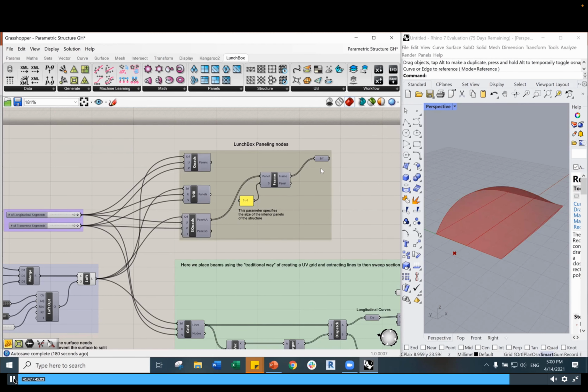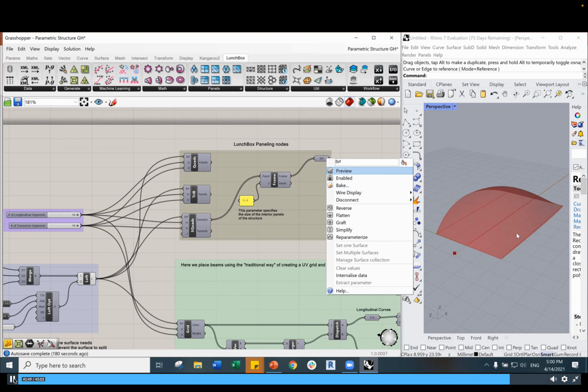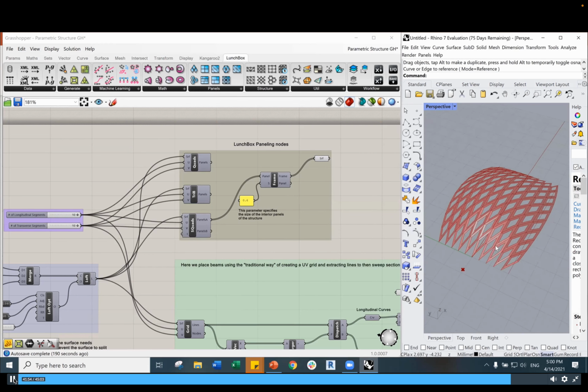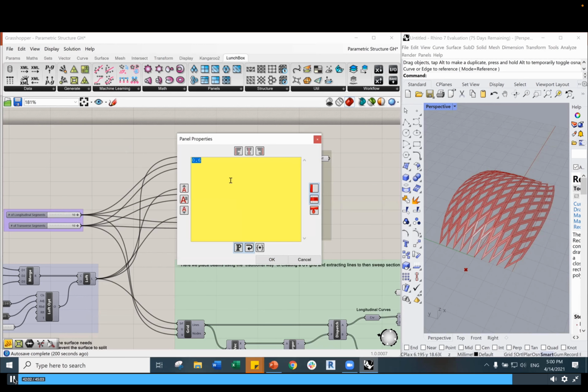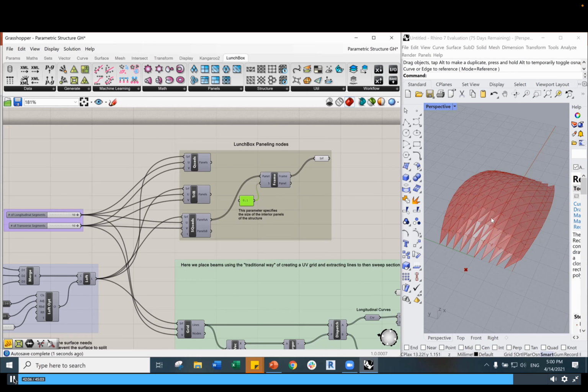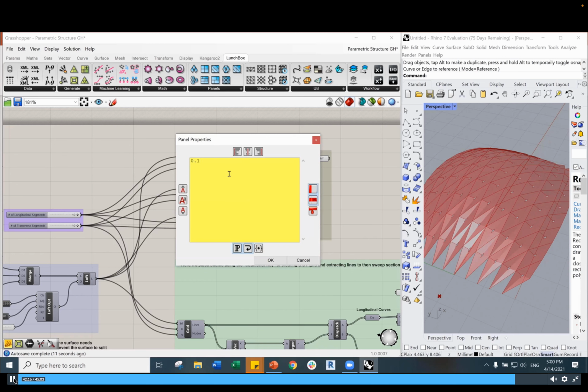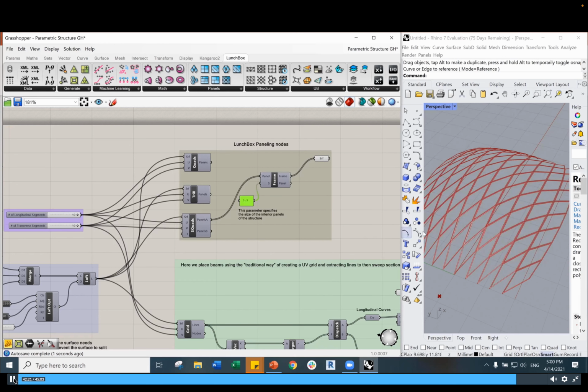So what this node is doing, it's just creating surfaces out of my loft. Like takes every panel, and based on a parameter of the thickness, it changes. So if I want my panels to be very thin, I would give 0.1. Sorry, the space. This is talking about the space in between, in the middle. So if I want thick panels, I would use a low value, and if I want thin panels, I would use a value that's close to 1.